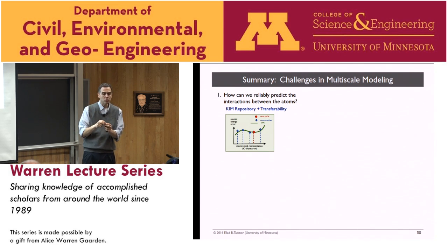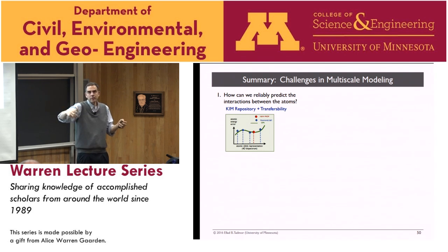Constitutive relations are almost always used to interpolate information. You do an experiment in a lab, and you stretch something, and then you put it in your finite element code, and you're only using it within the domain that you did your experiment on. And so as long as you're interpolating properly, it's reliable.